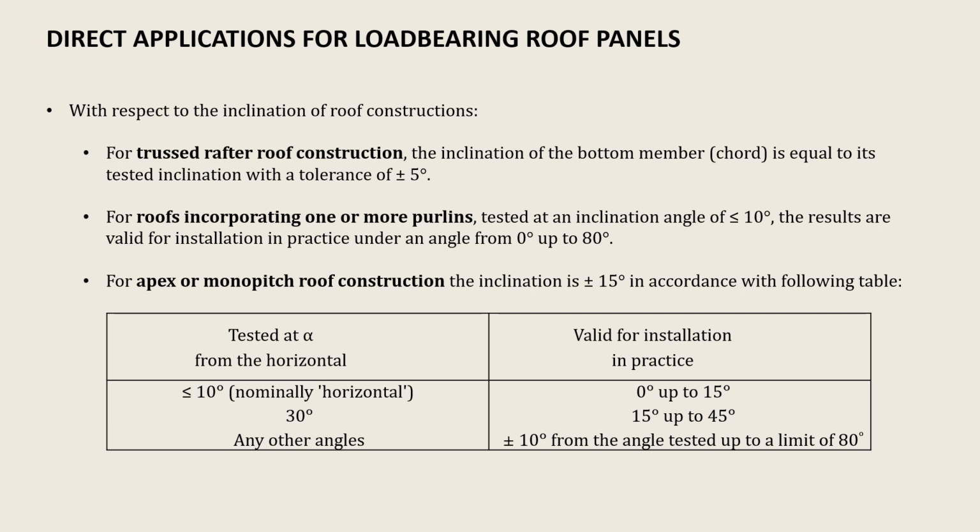The sandwich panel standard EN 14509 offers no additional rules for fire resistance direct applications in load-bearing roof panels, nor do external standards exist. Roofs also require classification for external fire performance, which may involve further testing as outlined in other standards.